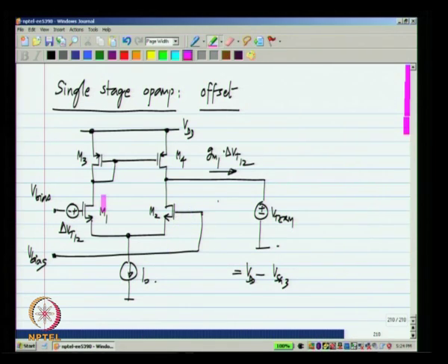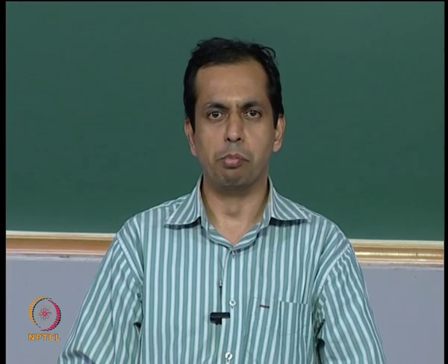Now, this is a very common feature. Usually, you have the input signal applied to some transistors. Any offset due to the input transistors will directly affect the circuit. This will be more obvious when we calculate the input referred offset, but it is also clear from this example. The offset between M1 and M2 appears directly as an input signal to the circuit.